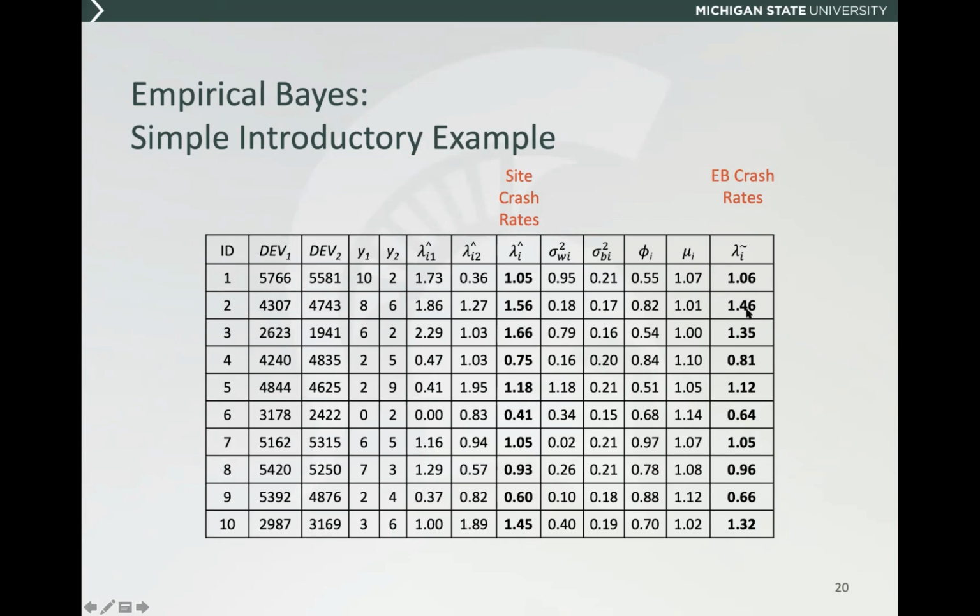And so if we extended this period beyond 2 years to 5 years or 10 years, these would probably be more reasonable estimates of long-term crash performance than this 2-year sample. Likewise, the same is true on the lower side of the spectrum. So if we're at 0.6 or 0.75 crashes per year, we also see relatively large differences, where those means are being dragged upwards towards the mean, because those sites tended to experience lower than average crashes.